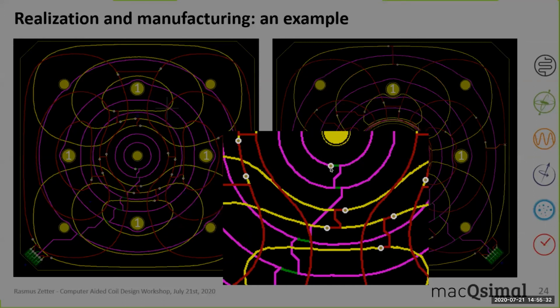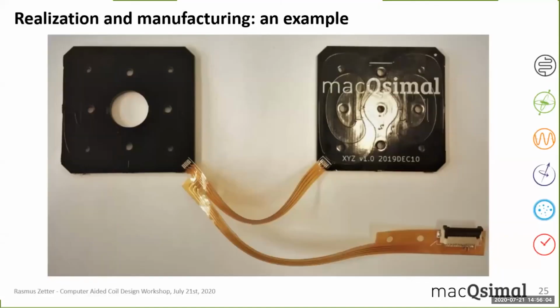And when we get to the center, we have a via, one layer down, and this green layer finishes the loops and traces back to cancel as much of the stray field as possible. And the same is true then for the yellow-red layer pair here. Right, so that's how we did that. And this is unfortunately quite a bit of manual work, not as much as winding the coils yourself, but still. And here you can see the finished product, which performed quite well.